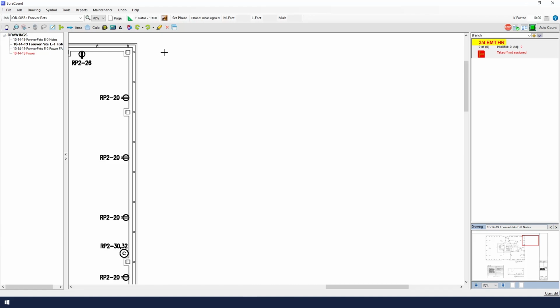With the symbol selected, we'll click to assign our first point. We'll hold down the Shift key on our keyboard as we assign our remaining points. The Shift key allows us to produce straight up, down, left, and right lines while measuring. As a note, if we don't hold Shift while measuring, we'll produce angled lines, which is okay in some cases, but in this case, we just want the lines to be going straight top to bottom and left to right. We'll then click our next point, and then a second, and then a third. Altogether, we just measured 8.41 feet, which is shown in the right sidebar under the symbol Info.